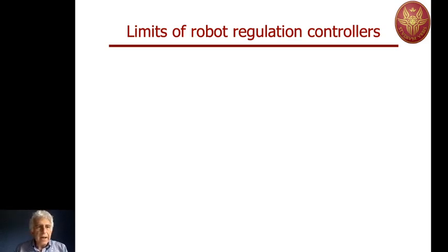So we have seen PD controller with gravity compensation, with gravity cancellation, PID with saturated error in the integral term, and so on. I would like to conclude this lecture on regulation mentioning a number of limitations of this type of approaches and introducing, therefore, a practical way used mainly in industrial robotics, but you can use it also in your research activity, on how to design a regulator for this type of task, which tries to avoid the limits that we will now illustrate.